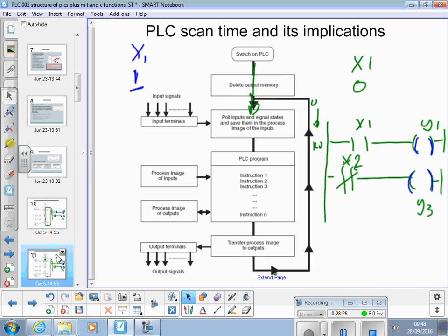Modern PLCs have the ability to use interrupts. The danger with interrupts in systems where control is important is it's difficult to test what's going to happen when that interrupt happens under every possible scenario. So that's something you tend to avoid unless you really have to do it. It's a very advanced way of programming, and only done if there's an advanced need for it. I've never had to do it.